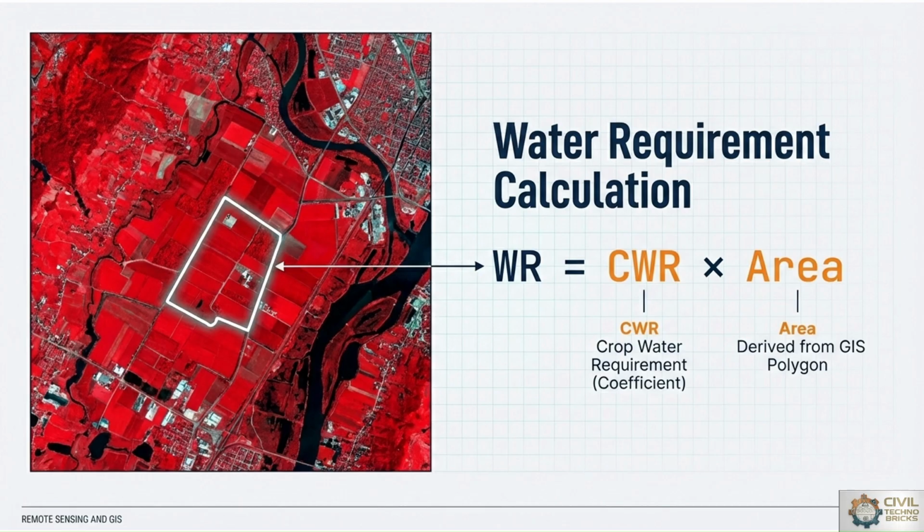By using satellite imagery to identify crop types and their growth stages, land use land cover analysis plays a main role, where meteorological data is also targeted, such as transpiration, evapotranspiration, and evaporation. So we can calculate exactly how much water is needed in each specific zone.